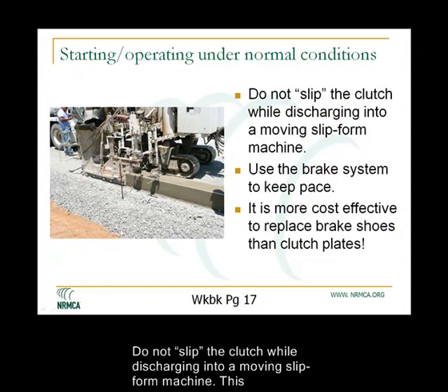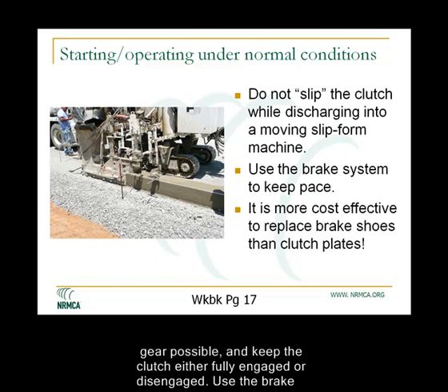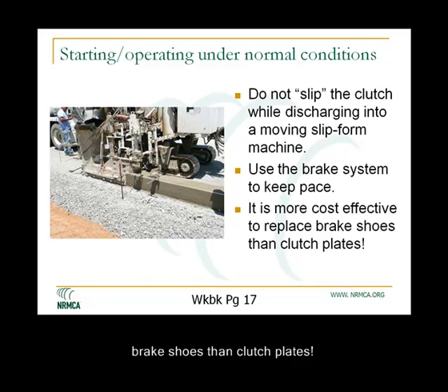Do not slip the clutch while disengaging into a moving slip-form machine. This creates premature and excessive wear on the clutch mechanism. Keep the truck in the lowest gear possible and keep the clutch either fully engaged or disengaged. Use the brake system to keep pace with the machine. It is more cost-effective to replace brake shoes than clutch plates.